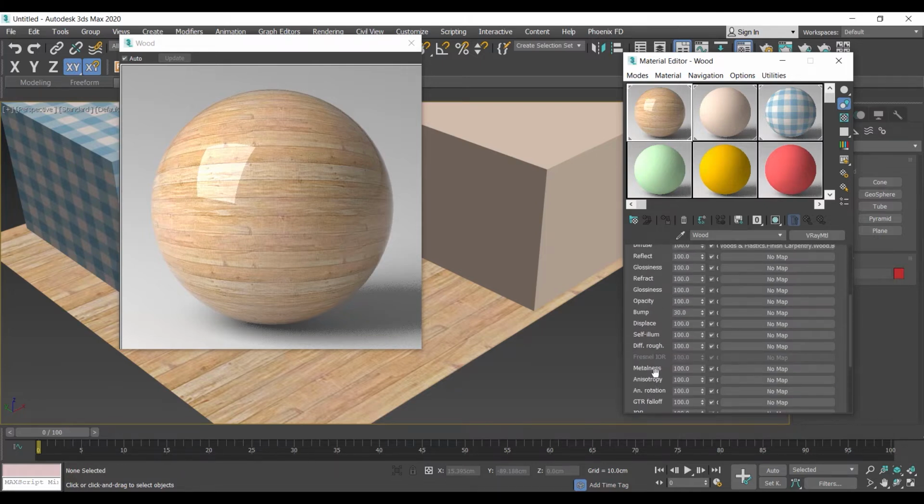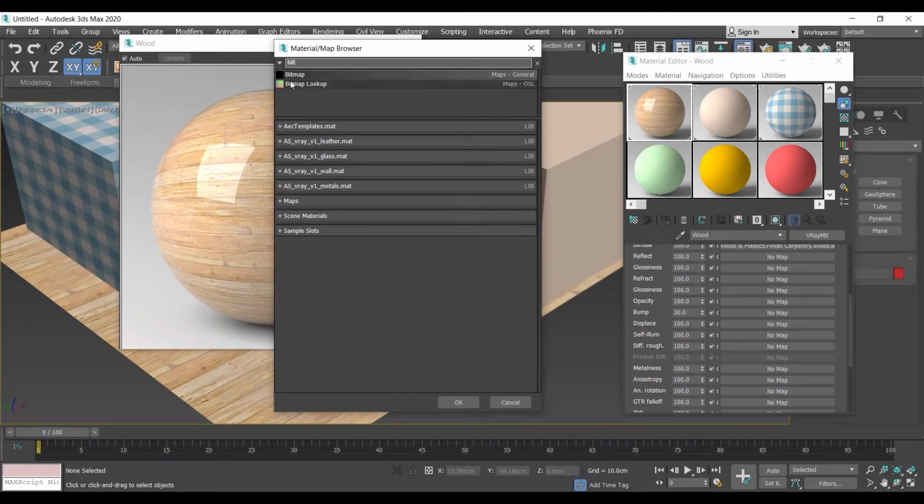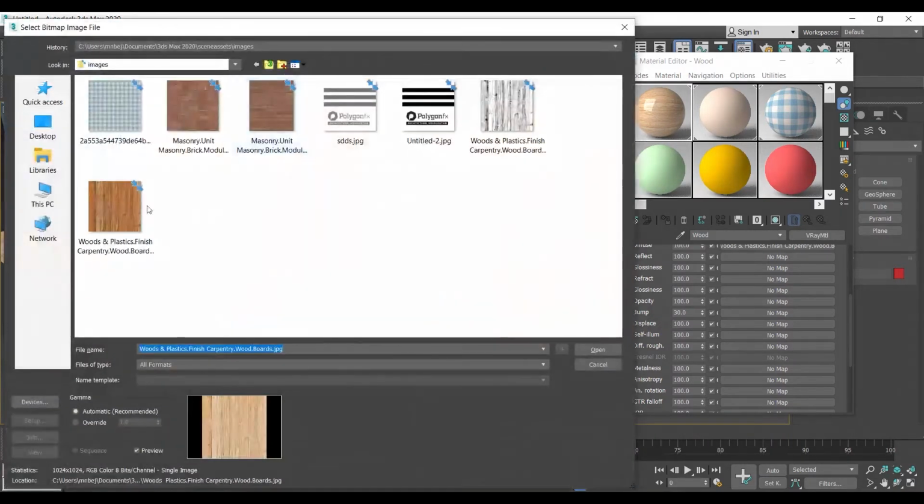also useful, it's called the bump map. The bump map is usually an image to be loaded as black and white. You can load a colored image, but when you import it to Bitmap, it will just convert it to a grayscale. So I'm just gonna go here, and I'm gonna go back to Bitmap. But in this case, I'm just gonna load the same image, but this one. Okay, so it's a black and white image.